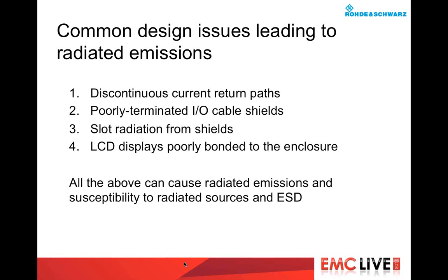So here's some common design issues which lead to radiated emissions, and these are all things that I have noticed in my clients' products, and in no particular order actually, but things like discontinuous current return paths, which really is an issue on the circuit board.